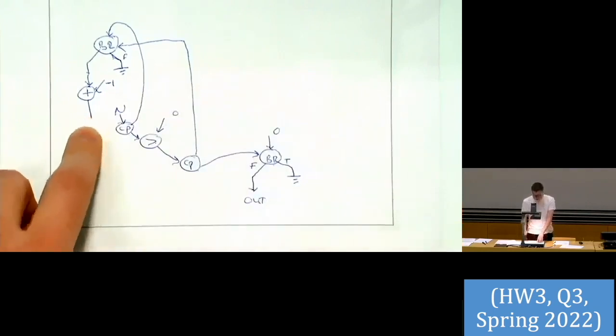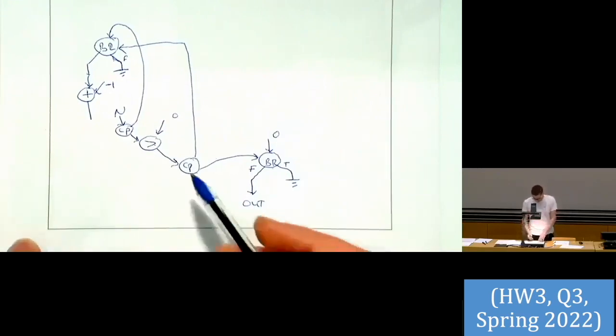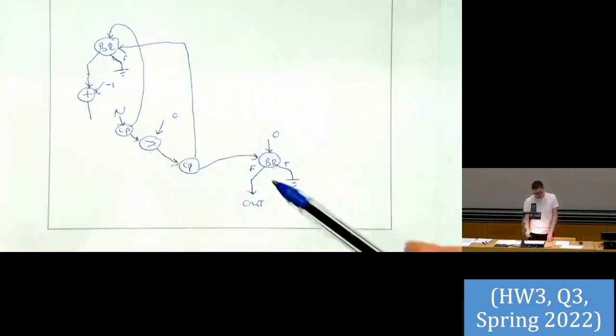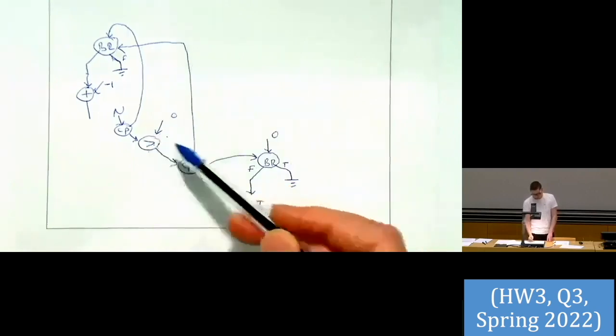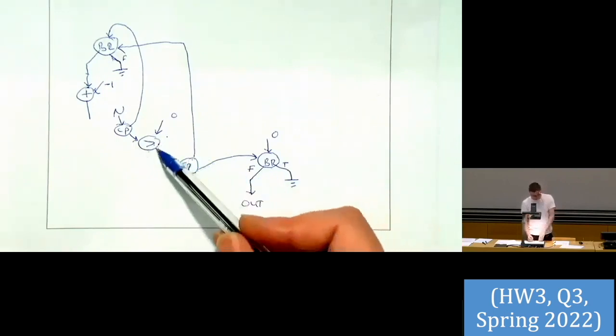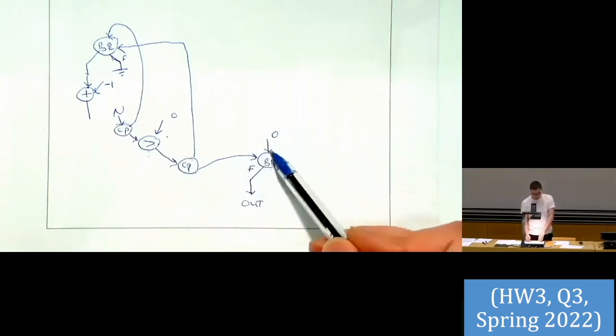And then basically, we will need to compare this n-1 again against 0, and see whether it's now equal to 0. We already have a comparator node here, but I will do another one. I'm not sure if it will be possible to reuse this. Even if it's possible, it will be too confusing to understand. So I'll just create a new one because this is hard-coded to this output logic here, which is receiving 0.